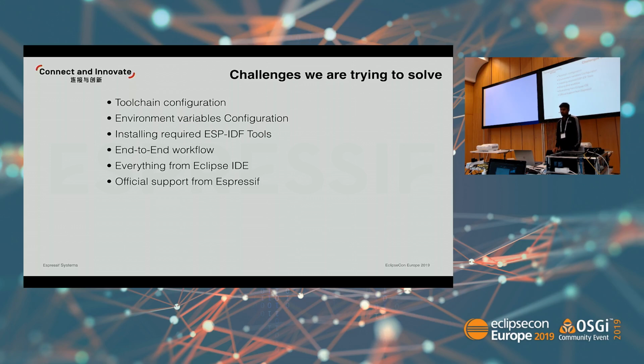And also, since someone wanted to program the ESP32, there are certain tools which we need to run, and those tools, as a user, they need to identify what version they need to pick from the GitHub, and for each ESP IDF version, they need to identify what is the supported version for that particular ESP IDF. So that's a bit tedious for any user who wanted to start. So with this we are trying to improve the onboarding experience, and also we support an end-to-end workflow. In the sense you start from installing the tools to flashing the device, and you can do your debugging and all that stuff.